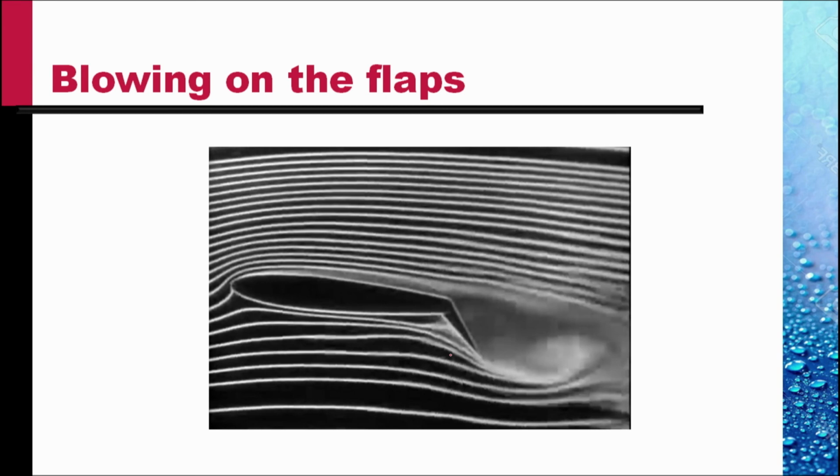To increase lift on the wings, we sometimes use flaps, which though they introduce more drag, give more surface area for the lift to act. They effectively increase the chord of the wing and therefore give higher CL maximum.